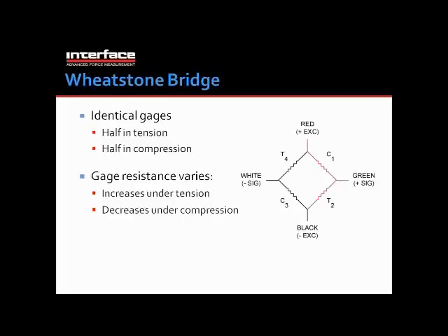So now let's talk a little bit about the Wheatstone Bridge. The Wheatstone Bridge is the electronic part, or the electric element, of a load cell. It is made up of 4 identical gauges. In this case, it can be made up of a combination of a number of strain gauges, usually 8, can be made up of 16, but in this case I have 4 for clarity purposes.